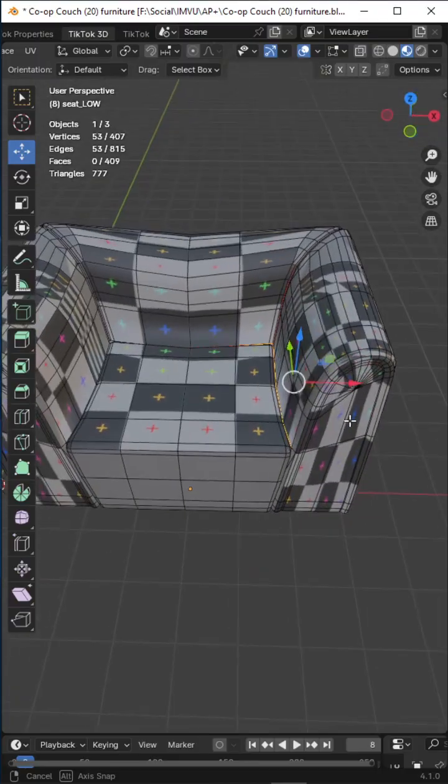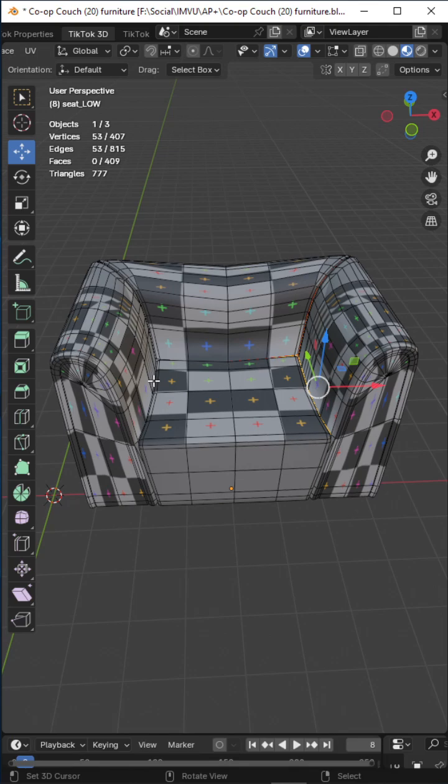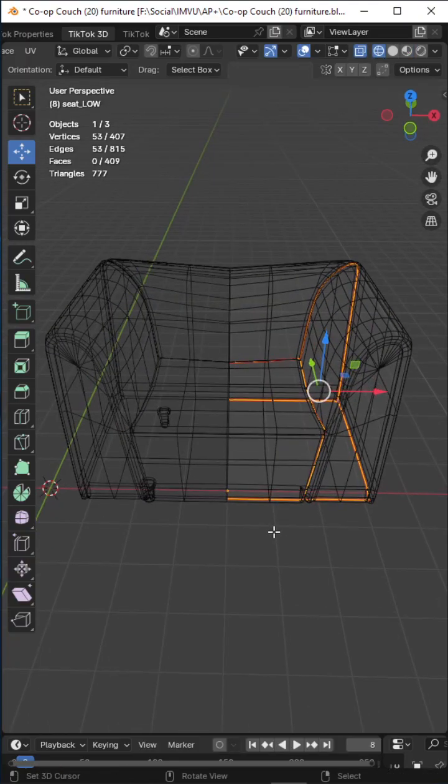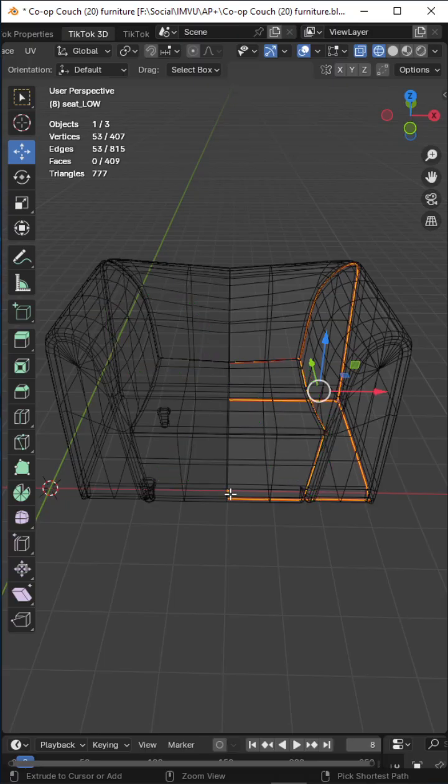When we're UV mapping, if we have a mirrored mesh, we have two options. We can either, as we just did, mark up the original side of the mesh, and then when the mirrored side is made real, it'll carry over the properties that are assigned to the original to the mirrored half.